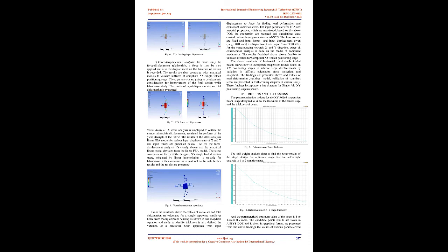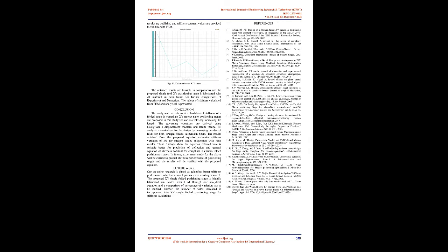Based on the above, the geometries are prepared and simulations were carried out on these geometries in ANSYS. The four corners are fixed and input forces and input displacement are given, in a range of 0.01 mm as displacement and an input force of 0.52 N, corresponding to the X and Y directions. After all consideration, analysis is done on the model of the compliant mechanism. The results furnished above show it is feasible to validate stiffness for the compliant XY folded positioning stage.